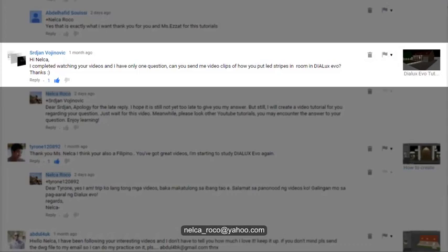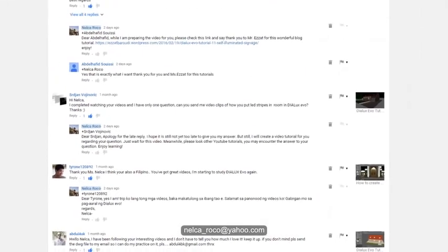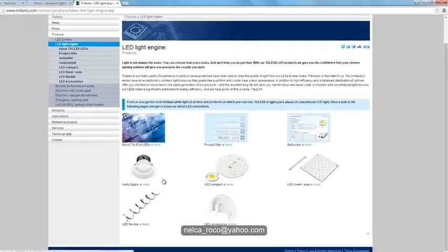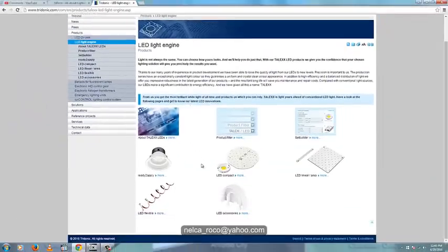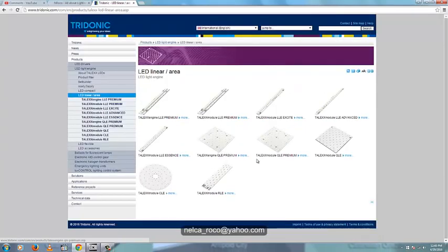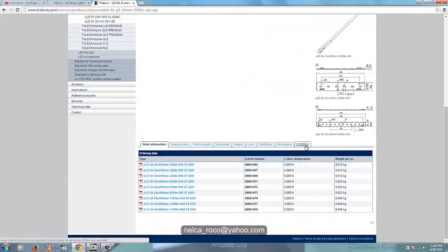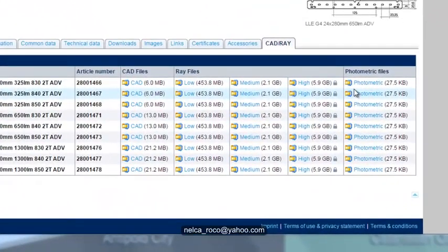Mr. Vojinovic, if you don't know any brand where you can get the LED strip IES file, I would like to suggest, yes, I'm not promoting, I'm just suggesting, to go to the Tridonic website and then go for the LED engine and select something. Let's go back and select something else. Maybe this one. Yeah. Okay. Let's go for the DiaLux engine and select maybe, for example, this one, and then go and yeah. Here you go. You can download the IES files for these LED strips.